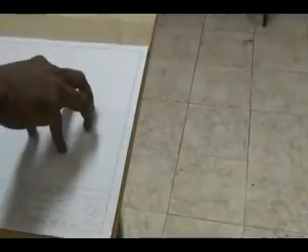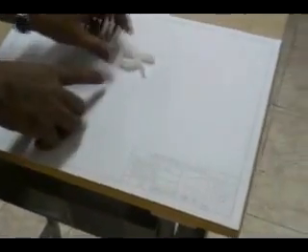Then you take your clip, you see the clip. Clip, you see you have a bent portion and a flat portion in the clip. Okay, the bent, how I am fixing, you look at the video. See, the bent portion should not come on the top. See, I am fixing it in a wrong manner, first of all. So you should not do that. The clip, how I am fixing. Okay, this is a wrong one.